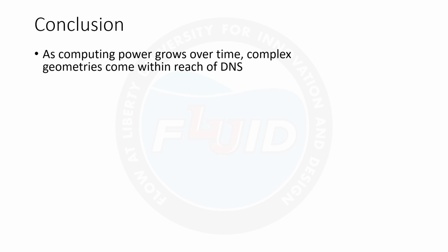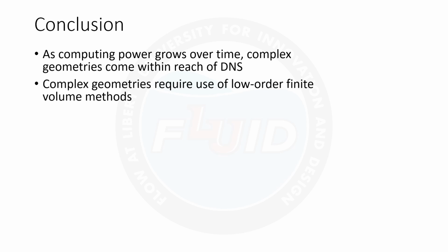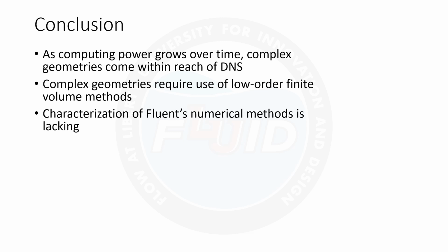Okay, as computing power is rapidly growing over time, complex geometries that were previously delegated to RANS or perhaps LES are now coming within the reach of DNS. These complex geometries unfortunately require the use of not only finite volume methods, but particularly low order methods, as opposed to the high order spectral element methods that have been used in the past. We found that characterization of Fluent's numerical methods is lacking, so we performed a study comparing the diffusiveness and dispersiveness of their momentum discretization schemes.